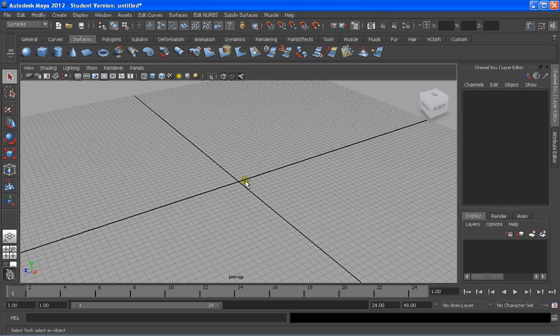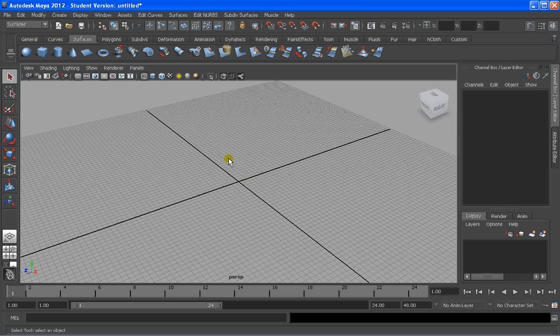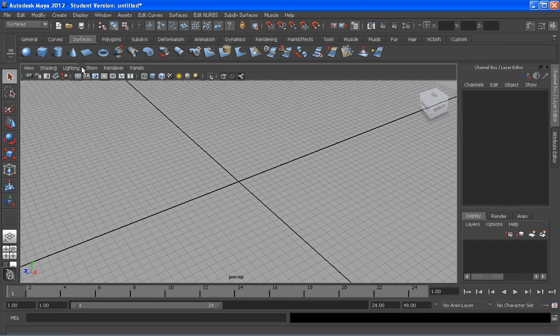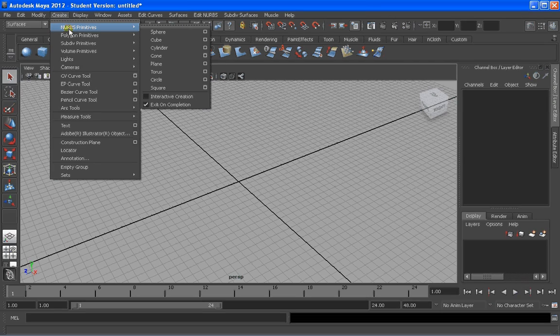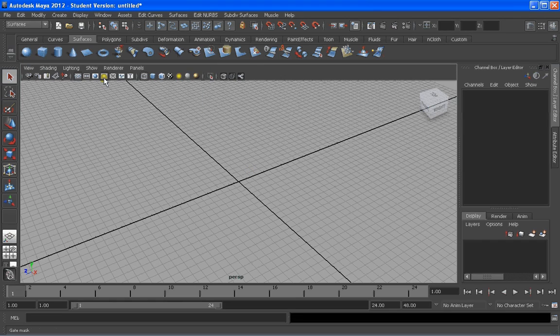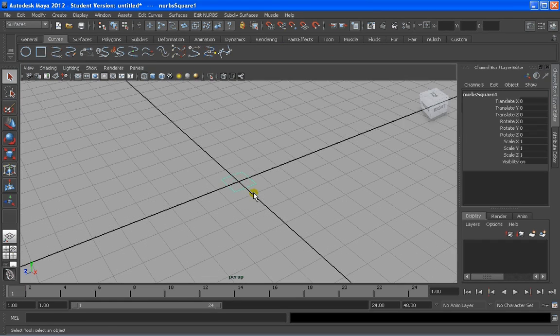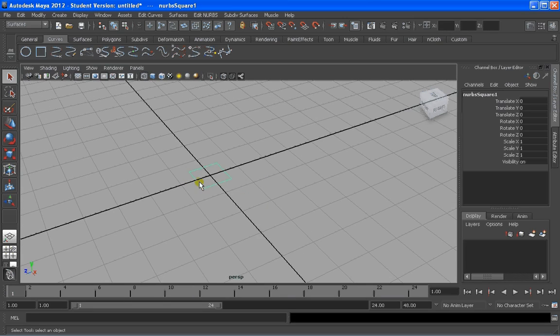First of all, I'm going to create a set of grids of lines that allows us to reference afterwards while we create the curves, so it makes it easier afterwards. First thing, remember if I press create and NURBS primitives and I set this without checking interactive creation, whatever we create, such as a curve, it creates whatever unit of the thing that you're asking for. In this case a rectangle 1 by 1 units set in center always.